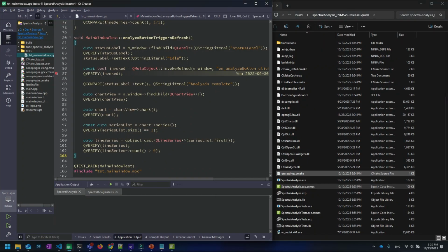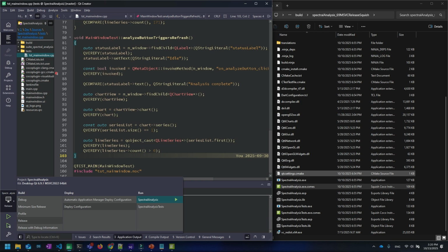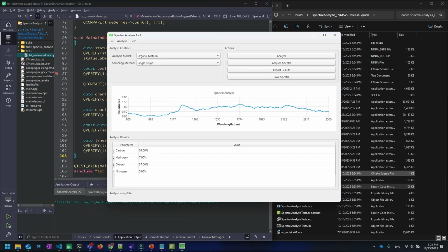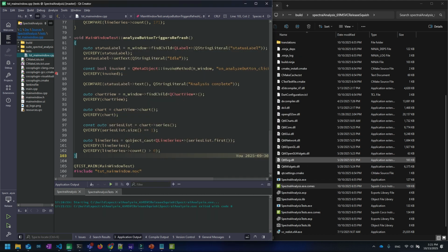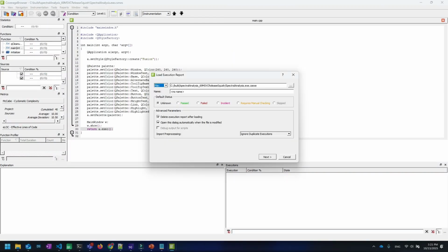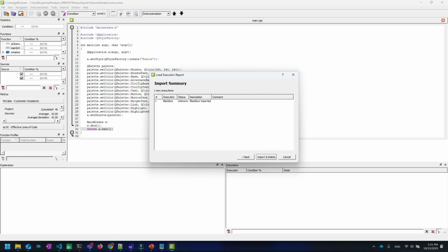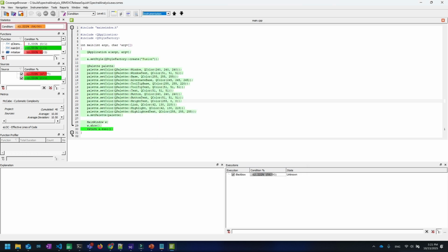Now I run the app interactively for black box testing. When I exit, Coco writes an execution report, a .csexe file. I load that report into the .csmes file, and the current run gives about 62% coverage from manual exploration.